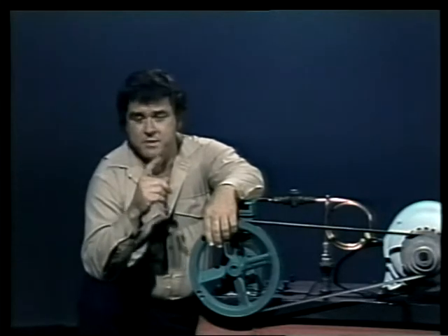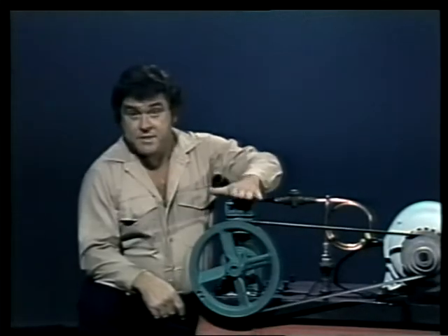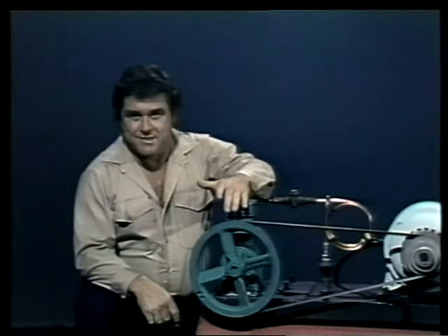We've been talking about one specific kind of positive displacement air compressor, the reciprocating type. That is, compressors with cylinders and pistons. Now, we're going to be talking about a couple of different kinds of positive displacement compressors: rotary screw and sliding vane compressors. We'll see what they look like, how they work, and we'll talk about the accessory equipment that keeps them operating efficiently. We'll start with the rotary screw compressor.